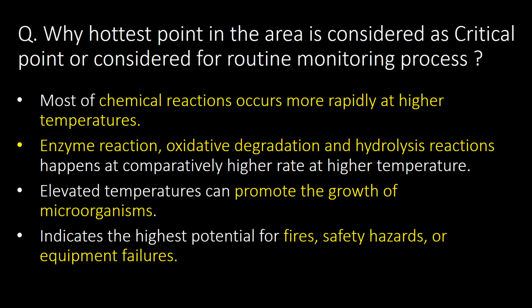The four major reasons behind considering the hottest point as a critical point are: first, most chemical reactions occur more rapidly at higher temperatures. Second, enzyme reactions, oxidative degradation and hydrolysis reactions happen at a comparatively higher rate at higher temperatures. Third, elevated temperatures can promote the growth of microorganisms. And fourth, higher temperature indicates the highest potential for fires, safety hazards or equipment failures.